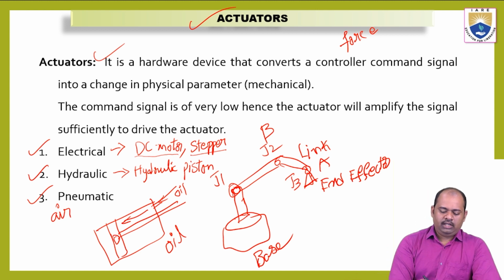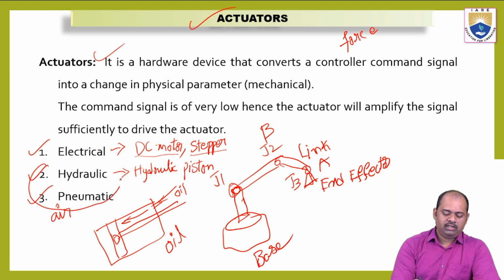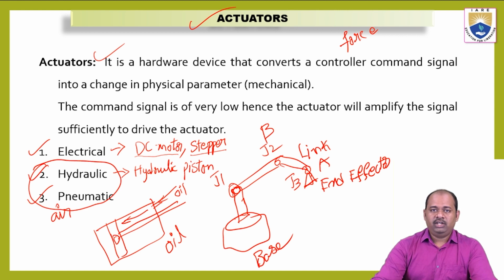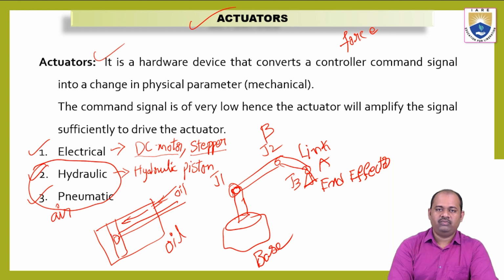Okay, and another thing, comparing the hydraulic and pneumatic actuators, hydraulic are more reliable because the failure in a hydraulic system is very low when compared to pneumatic systems, because whenever the air leaks, the piston inside the cylinder will immediately go back to its normal position, which will sometimes cause problems, or it may cause a machine failure.